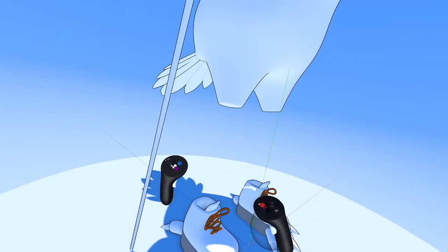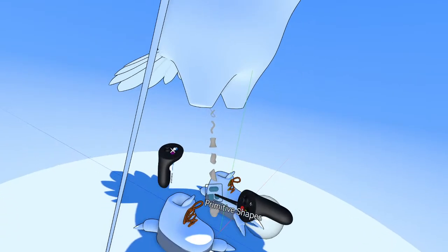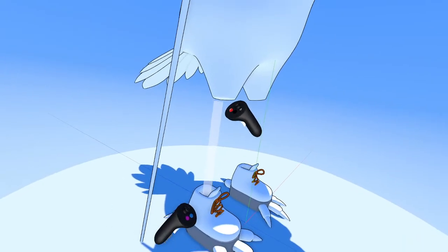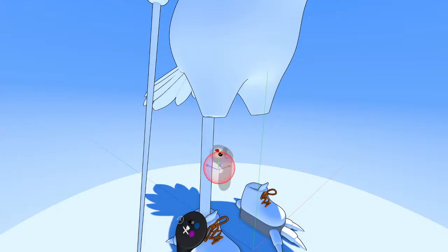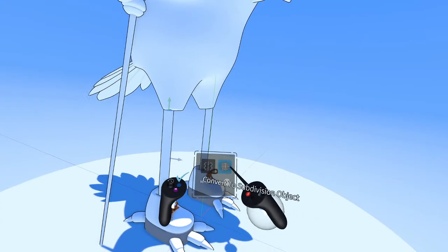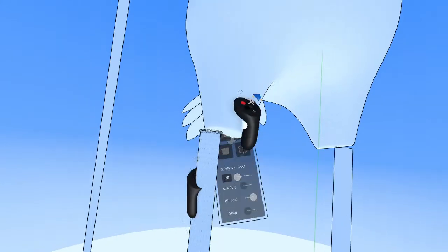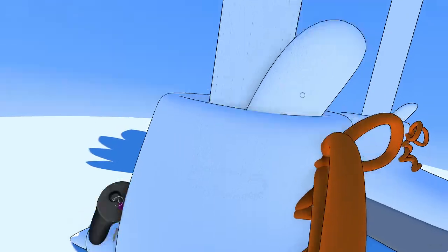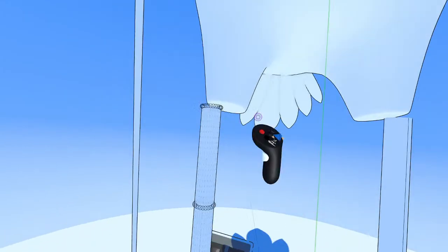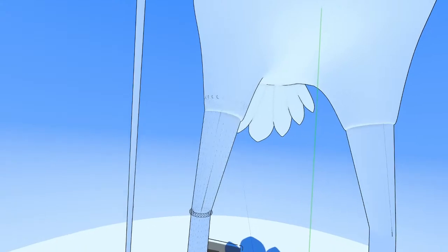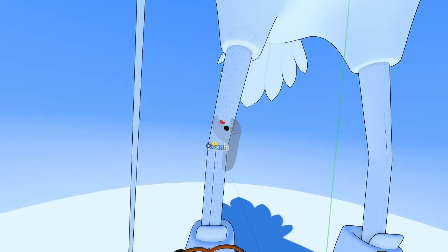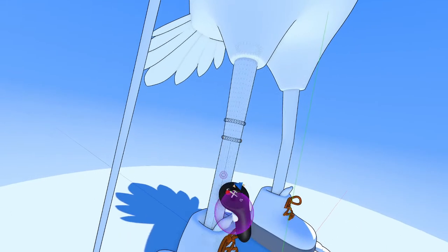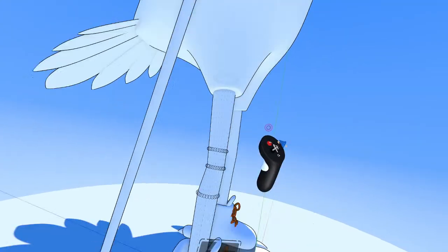So in this case, I'm going to delete that and just rebuild them using a primitive shape, a cylinder. We can just drop that in like this. It doesn't need to be exact, just a shape to start off with, and then convert that to sub D. Once we've converted that to sub D, I'll delete the faces because it's easier to deal with. Now we can drop in edge loops, position these things, and scale them up and down using the joystick on the right hand controller, and just get something that's a lot better looking.